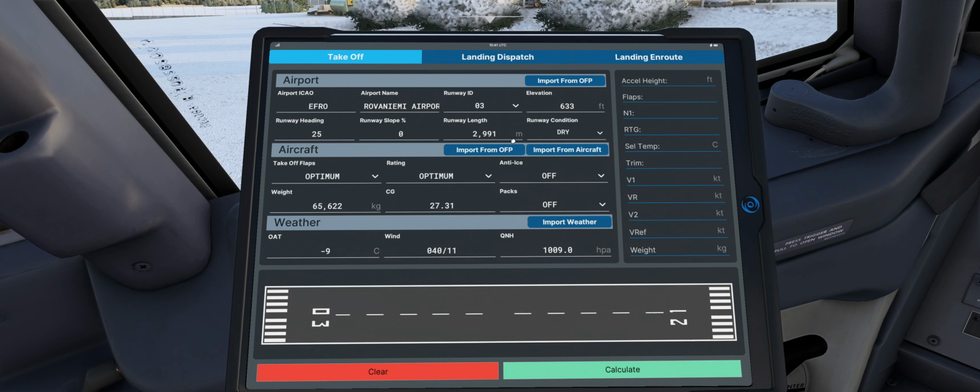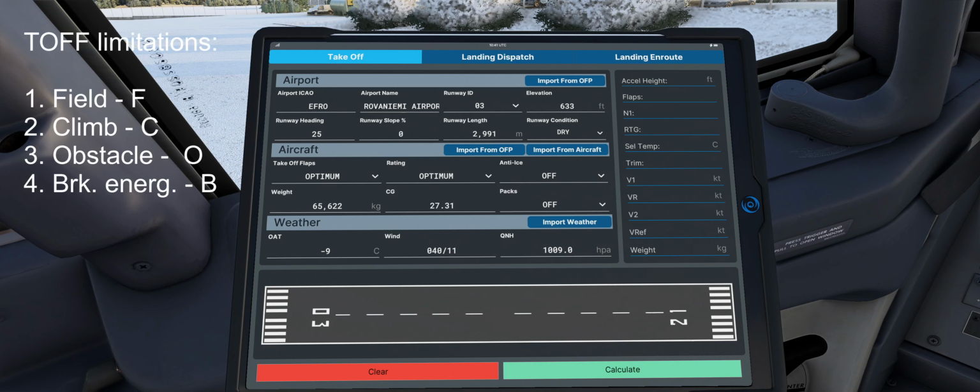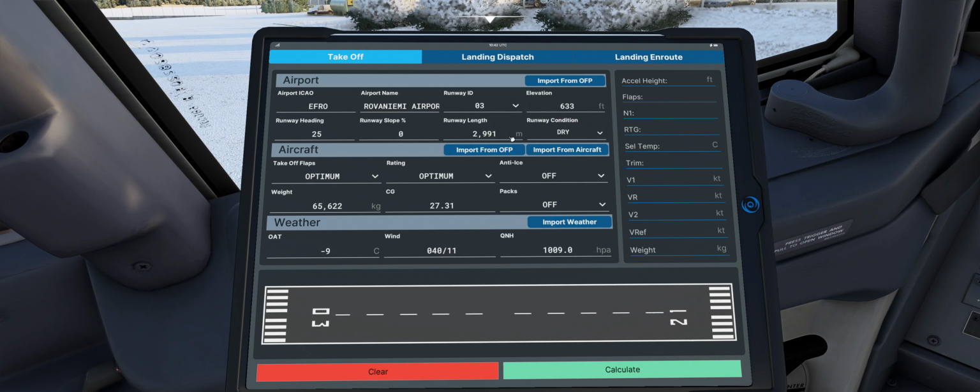Runway length: in real calculations you use not only the takeoff run available, but also the takeoff distance available, because it really matters if you have a runway safety area behind the runway threshold. You can increase your payload in some circumstances if you have a larger takeoff distance available. But anyway, here we are using the takeoff run available. If you have, for example, a runway intersection, you need to adjust for your intersection, but we'll go through the full length.